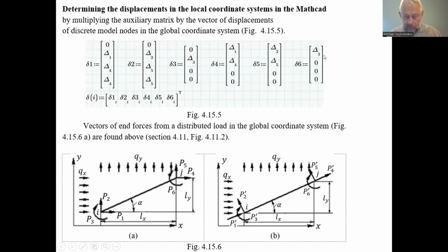All other angular displacements at the ends of the finite elements are out of our interest, because the third, inclined finite element is embedded and does not experience angular displacement, and the fourth finite element is hinged, so there is no distributed load and bending moment in the hinge connection of the fourth finite element.